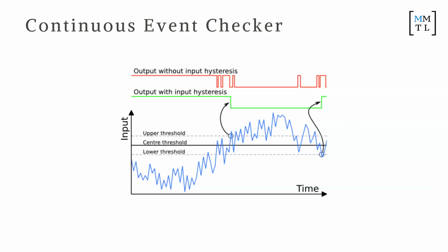So the trick is actually to have two thresholds, called a lower threshold and an upper threshold. This is a pattern in engineering called hysteresis, which basically says that at this point here, you don't do anything. At this point here is when you turn it on, when it passes the upper threshold. Then this threshold kicks into the lower threshold, and only when it drops below this lower threshold do you turn it off. Does that make sense? The same applies in the other direction. Once you pass here, then this upper threshold kicks into place, and the behavior of the machine doesn't change until it passes back past this dotted line.